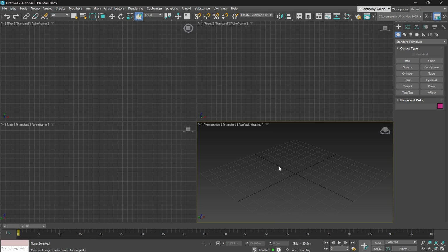and therefore. Now, there are 4 main types of shapes in 3ds Max. First, shape primitives, which are very similar to 3D primitives. Second are editable splines, often called lines, which you can modify directly. Third, freehand splines, which let you sketch freely right inside the viewport for more intuitive drawings. And finally, NURBS, short for non-uniform rational B-splines, a somewhat older technique that still exists. Amazing! Now that we actually understand this, let's take a look specifically at each one.